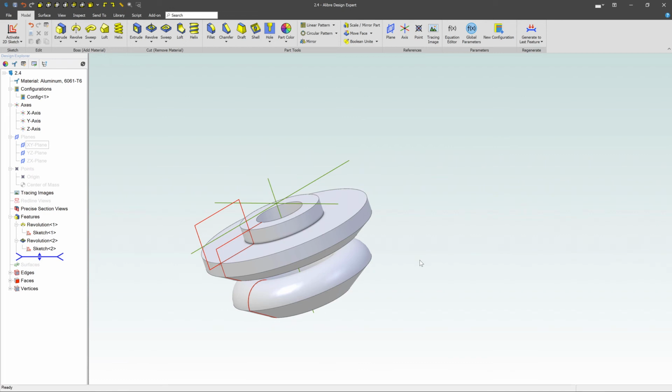Almost like you think about in a lathe, if you're going to turn a part, you want to start with a big piece of round material. You're going to machine away or turn away that material on the outside to get to your final shape. This is a great way to think about revolved cut. It's a material removal process, and it's very effective in viewing and seeing how parts would actually be made in the real world in a turning center or a lathe, just by removing material and defining what those shapes are.